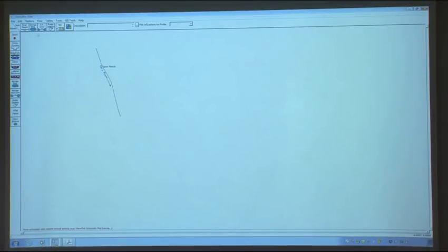So the next one is to click on the river reach again and try to locate it close to the end point. Then place the first point, the second point, or a number of points. At the end, double click on that. Right now you already have Fall River, but for the reach, somehow for me, maybe I selected too close, it just takes a default name.